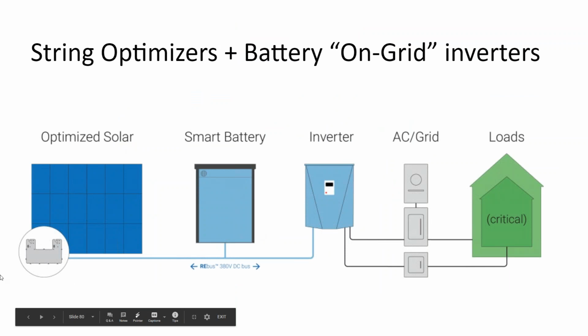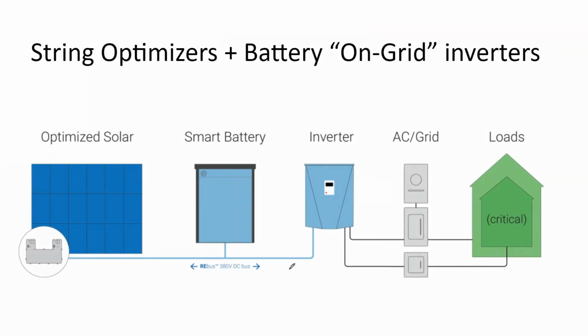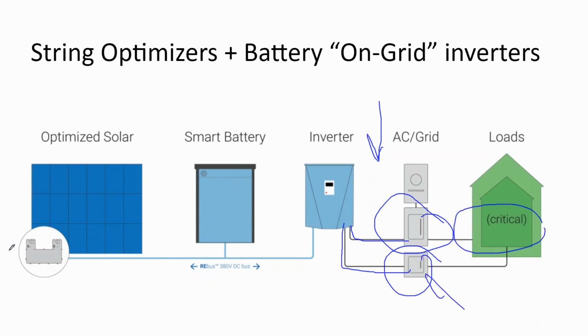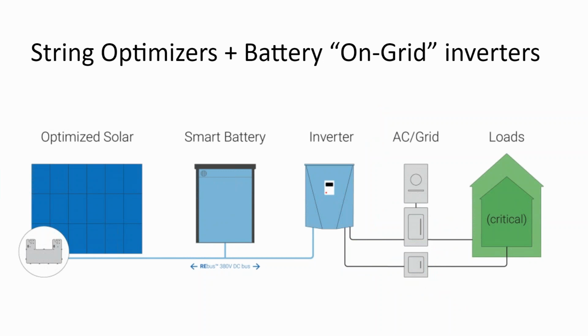But it's one thing to say these wires are all tapped together into the grid, and another thing to say we're also adding a battery and doing backup loads. Basically, if your hand is reaching out and grabbing a hold of the electric grid, it has to let go of the handshake in order for you to power backup devices. So here's a simplified diagram, and it shows a battery inverter connected to the grid, and then it also shows this kind of weird thing, and it references a critical load panel.